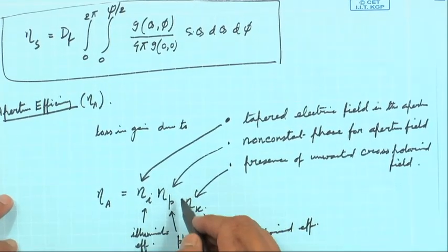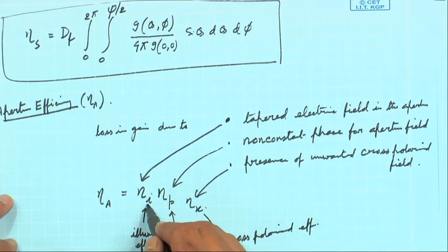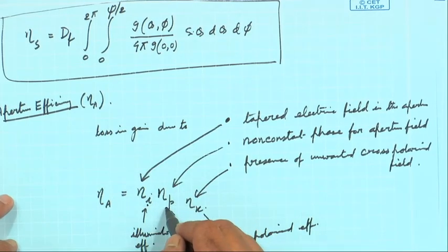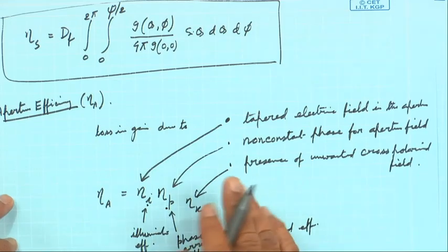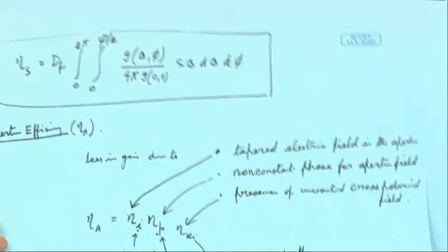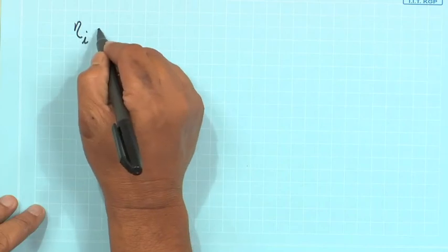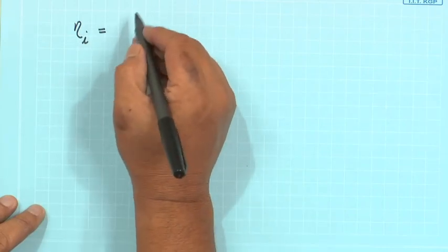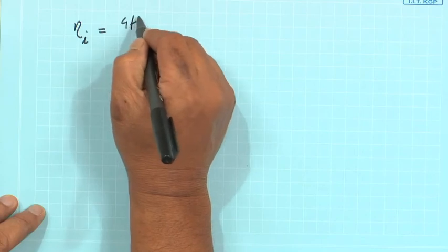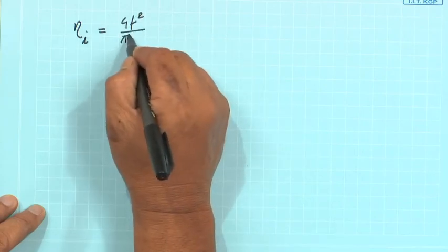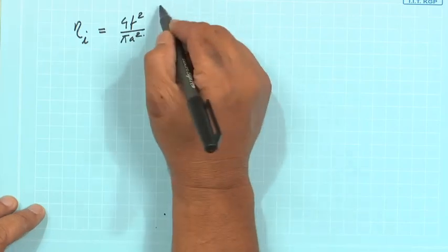So, there is a long list of things. So, we assume while deriving this illumination efficiency that eta p and eta x are 1, later we will put their values. So, under that assumption it can be derived. If anyone is interested, please see in the course page, we can upload the derivation, but finally what we need is that eta I, the illumination efficiency, becomes an expression something like this.